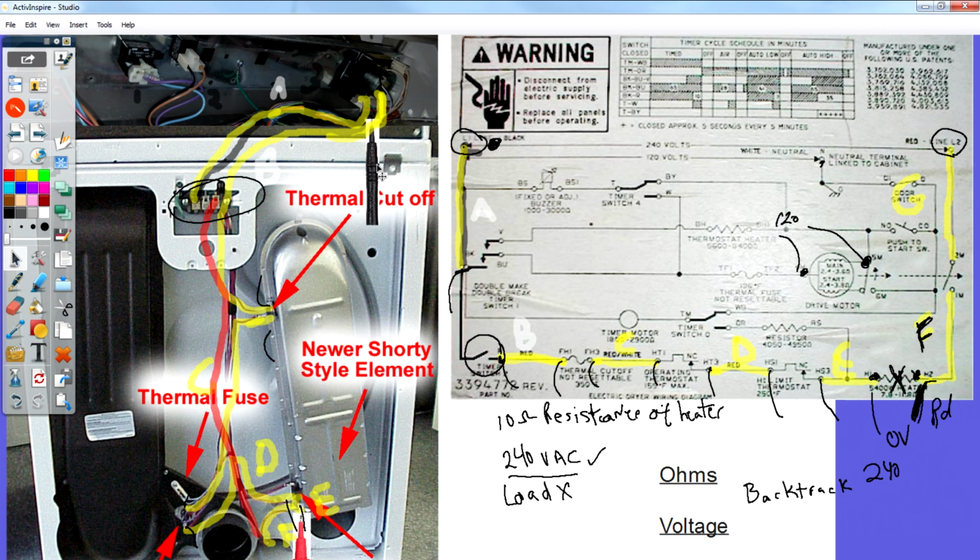I go to this one here, and all of a sudden I have voltage. The red one is always here on the meter the whole time. I've never even moved it. I'm just taking one lead, bam, bam, bam, testing one at a time, saying, where is that electricity? And I lost it here.